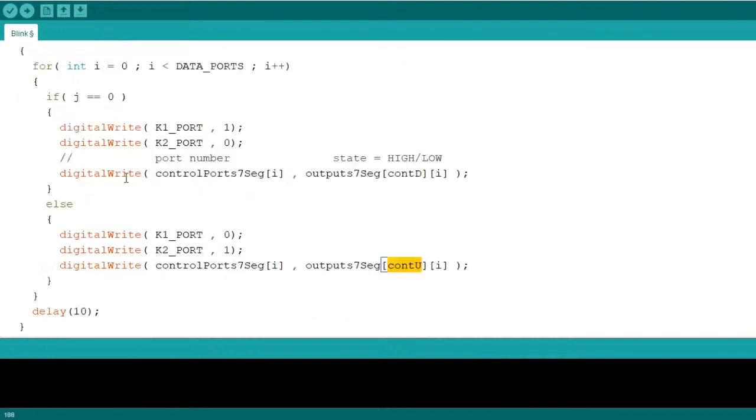So after I configure the tens 7-segment display, the one that is located at left, I should configure the right 7-segment display. How? Turn off the first transistor and turn on the second transistor.